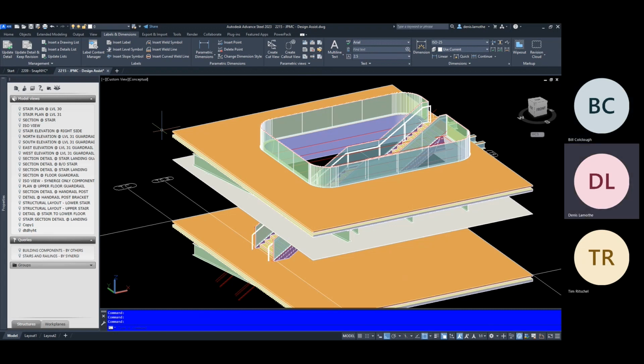So, yeah, for your general stair layout, you're right. The macro would space things out, say your stair nosings, for example, your tread spacings and all that would automatically be calculated from your first work point at the bottom of the stair to your top point, either your top landing or your top of the floor. And it would take that overall height and divide your risers equally and remodel it.